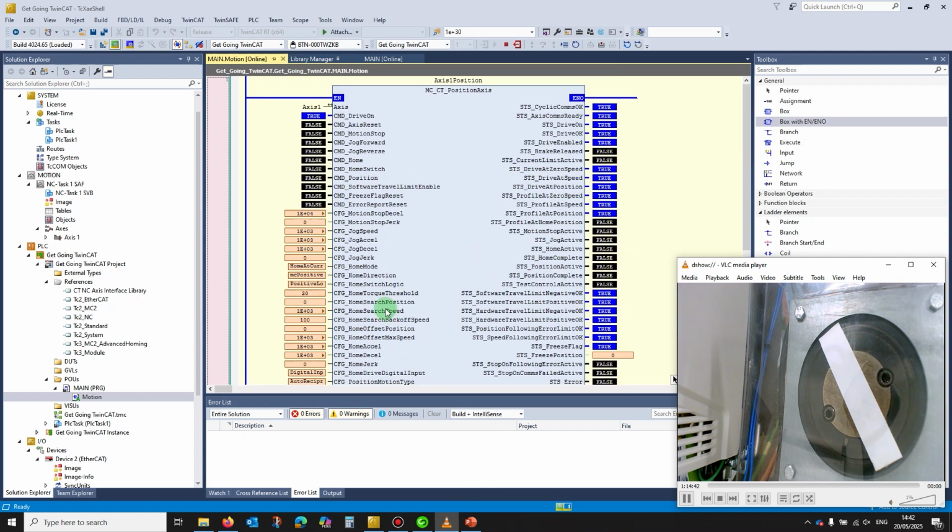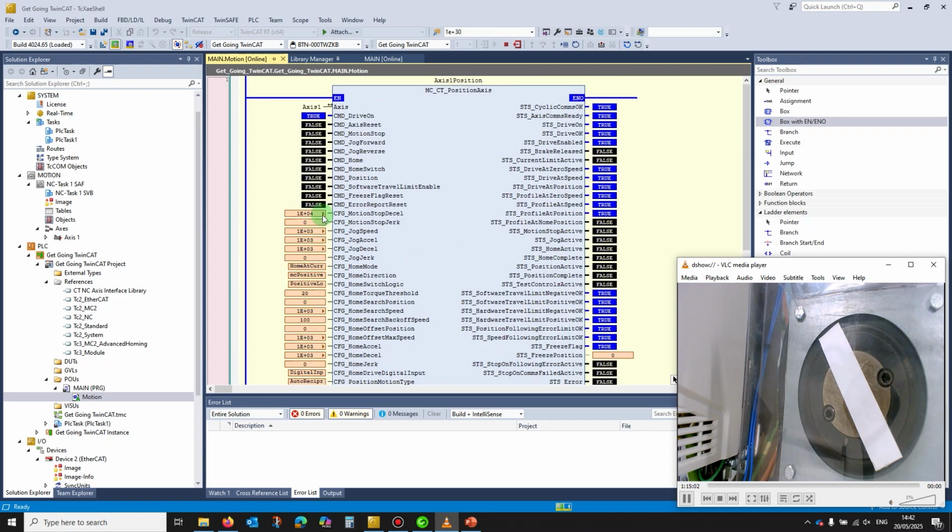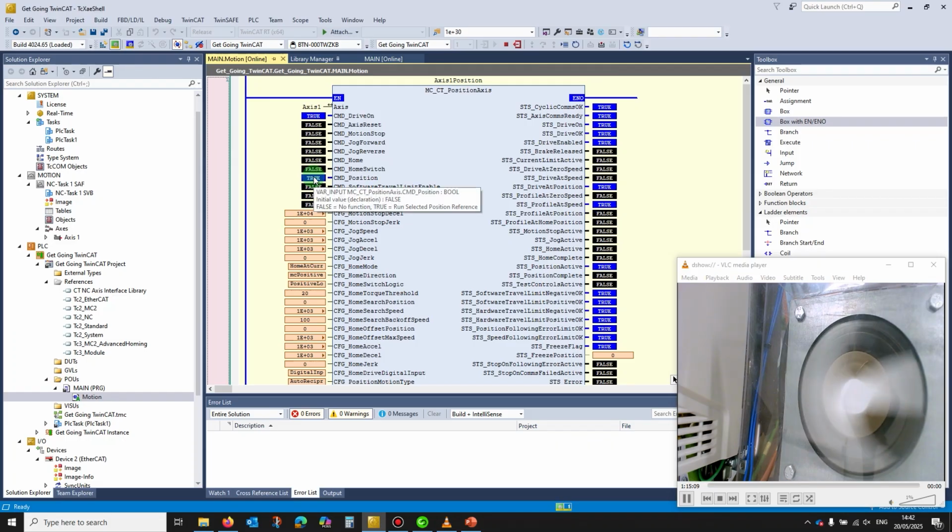So what we need to do now, so we've set up our motion. So we've said we want it to go back and forth by 2 revs. The maximum speed that it's going to reach is 5,000 units per second, and then we want to get there at 50,000 units per second acceleration and deceleration, so fairly rapid. Let's just turn on position reference. Oh, there we go. That's perfectly good enough for what we're trying to achieve.